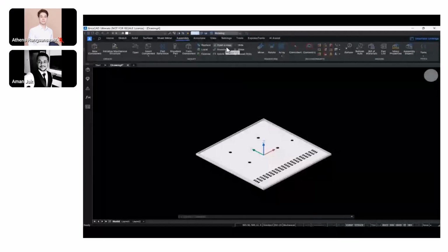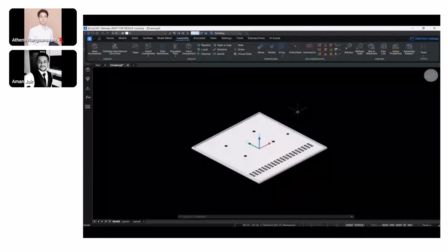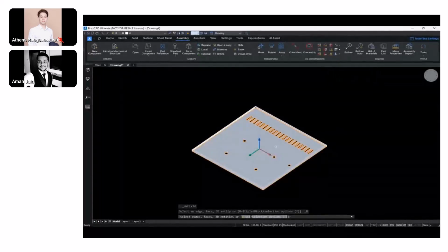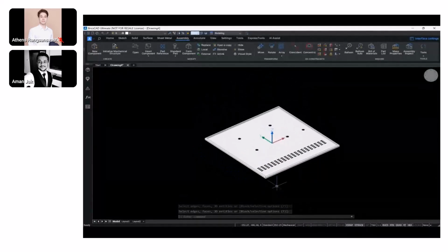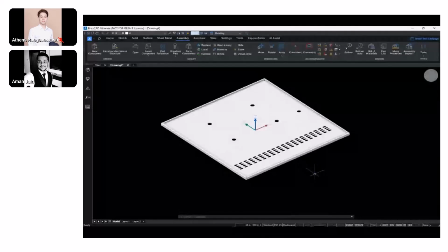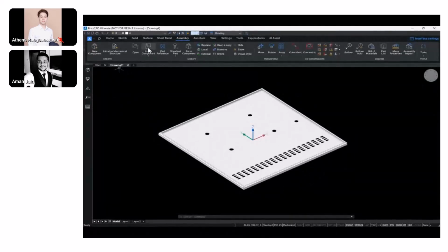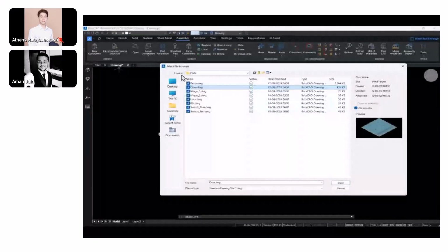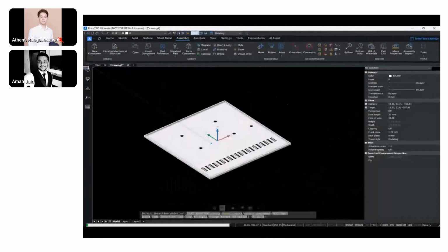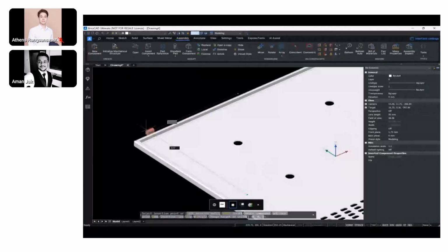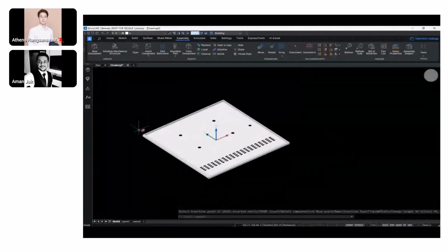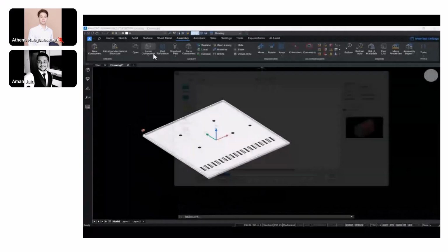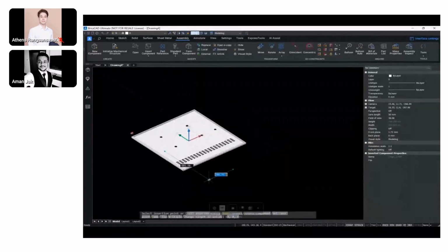And I just changed the representation to modeling. Okay, and then I have some additional components in place which I'll insert. Okay, and in BricsCAD, since it does not differentiate between a part and an assembly through an extension, they are all DWGs. I can simply insert a component using the BM insert command, and this is the one that I want to insert. So these hinges would essentially be on the door, and then we have a separate hinge for the body as well, which will mate together to create our complete enclosure body. Right. So we add 2 instances of it.